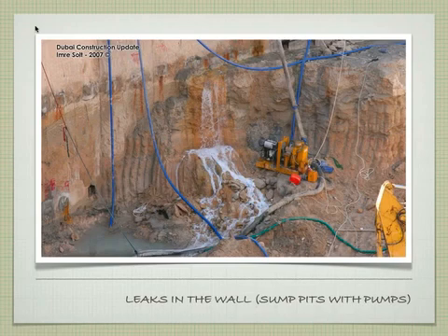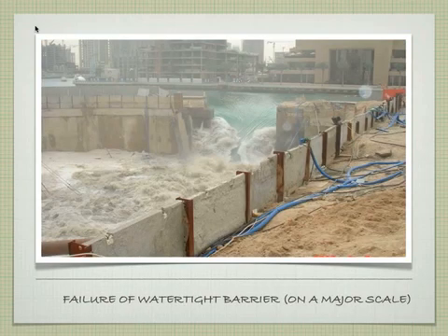So we're getting some leakage, and this is a little more than a little leakage. It's kind of challenging. So this pump is here, here's our tubes going to other pumps running up, and we're trying to suck out. There's a sump pit right here. We're trying to suck out all this water and get rid of it. So again, slurry wall. If I were building this and there were these stains coming down, I'd start to get a little nervous. I don't know about you, but I'd be a little nervous. So maybe you didn't do a good job dewatering and something like this might happen.